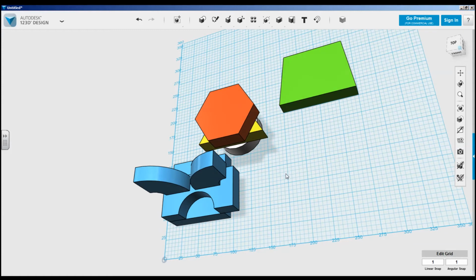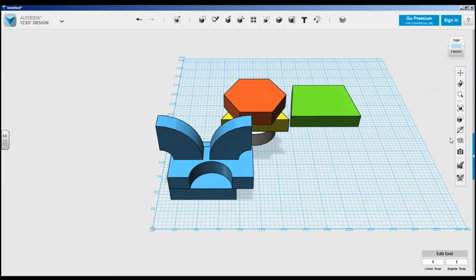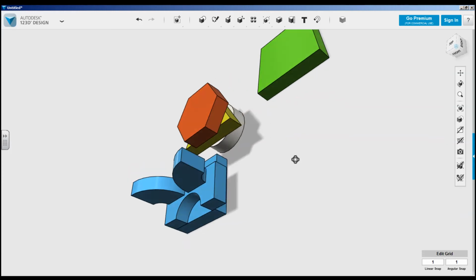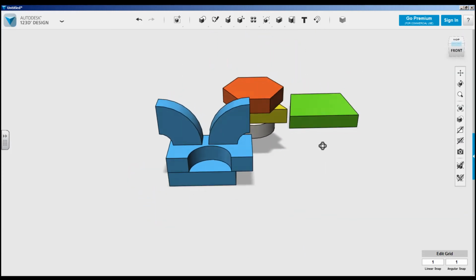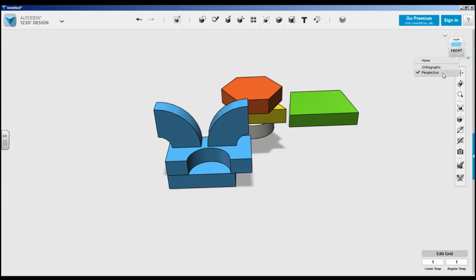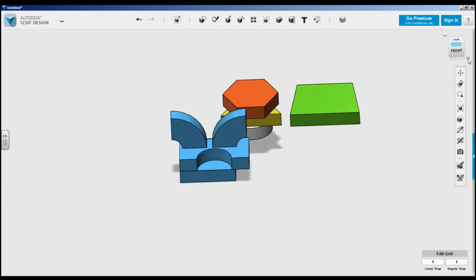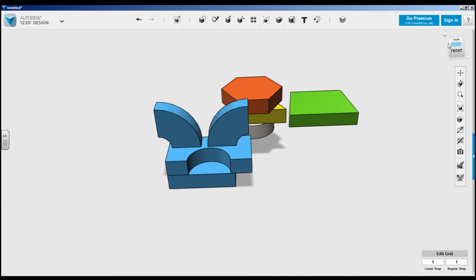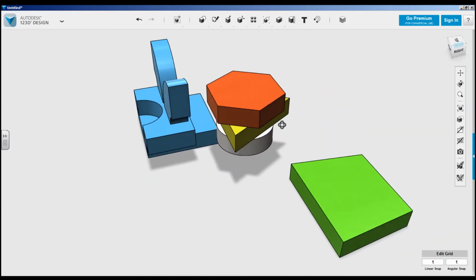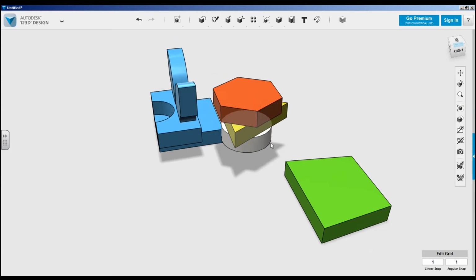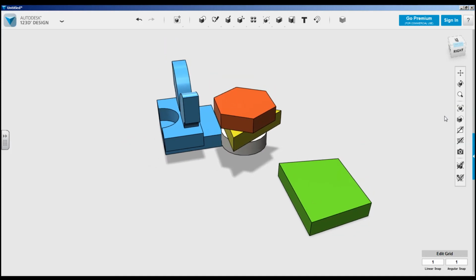The other thing you need to keep in mind is setting up a nice screenshot to then put in Photoshop to show your preview of how your building will look. So to do this, make sure that perspective is turned on instead of orthographic, and then experiment with different camera angles to match the photo that you've got off the internet from worksheet 6. And then the new updated version, there's a capture screenshot button. Otherwise you'll have to use print screen and then paste that into Photoshop.